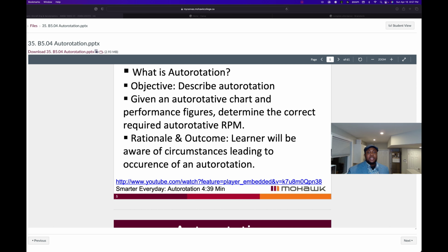Once we've successfully flared the helicopter and reduced its momentum falling towards the ground, the next phase would be approaching for touchdown. But before we touch down, we need to move the cyclic stick forward so that the helicopter's attitude is restored to prevent a tail strike. Once forward speed is reduced, the cyclic is moved forward to put the helicopter in its landing attitude. The collective is added to cushion the touchdown right before the helicopter touches the ground.